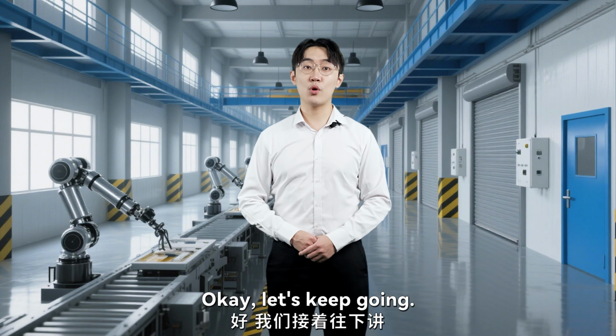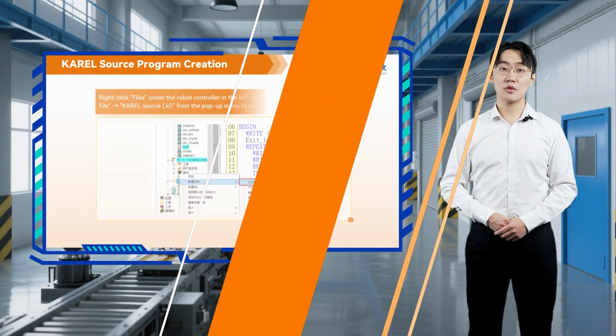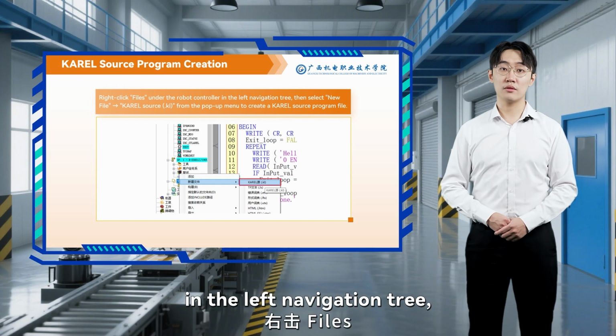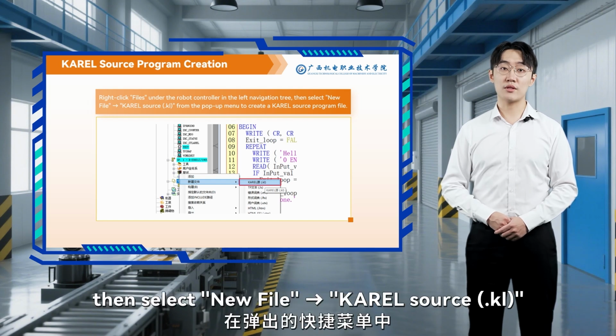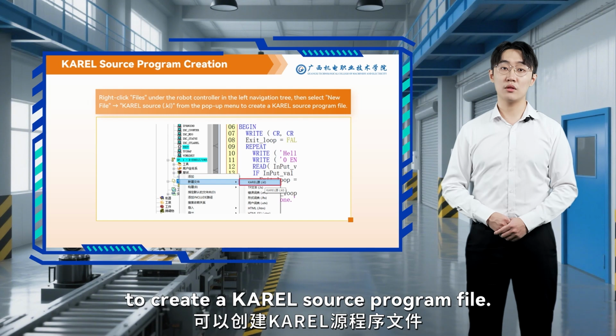Okay, let's keep going. Next, we'll learn how to create a KAREL source program. Right-click Files under the robot controller in the left navigation tree. Then select New File, KAREL Source, .KL from the pop-up menu to create a KAREL source program file.